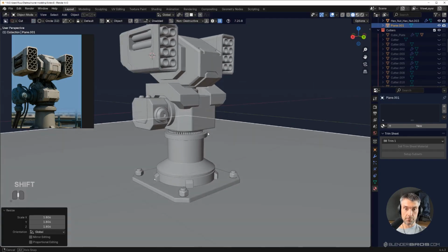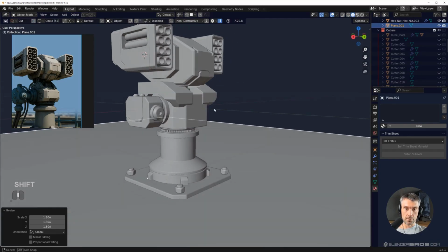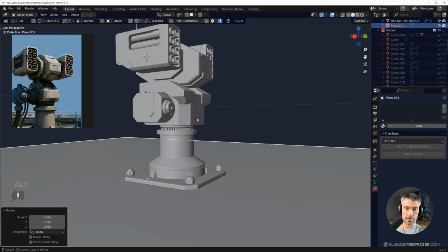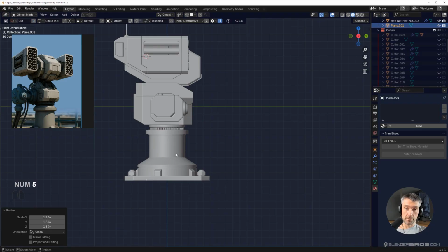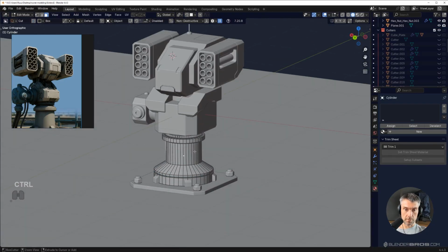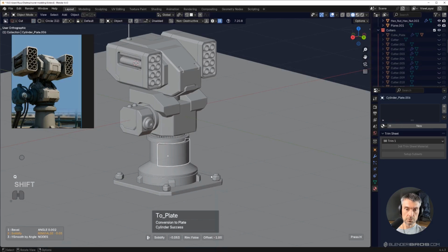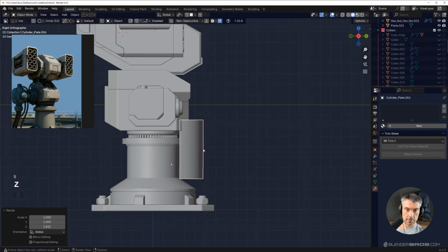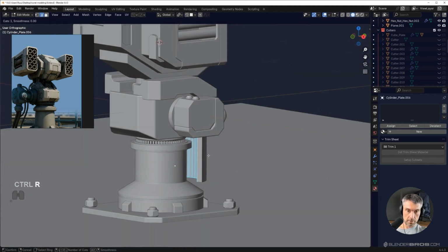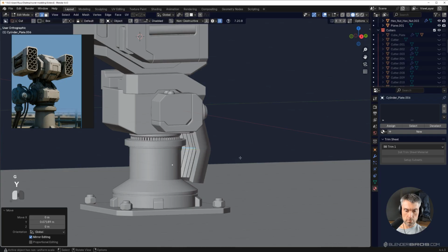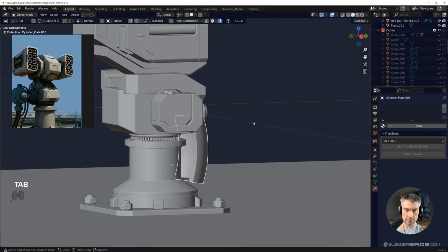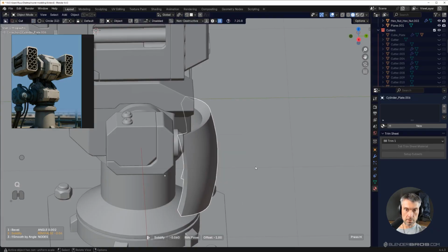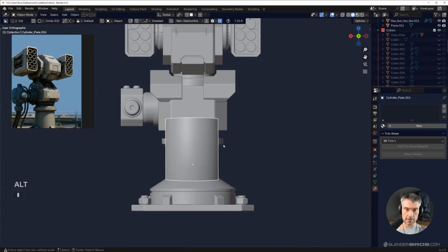It's really cool. Another thing you could do, you could add an armor here in the front that's going to be protecting the rotary mechanism, kind of like a shield here that's going to be rotating with the mechanism. So what we could do is grab these, and Shift Curve Extract them and move them somewhere here, make them larger. Run loop here, move it forward, bend it like this. And you got yourself a shield.